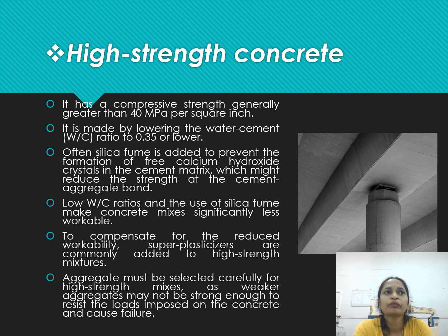So basically, when you reduce the water, look, water is added first of all for bonding. The next reason for adding water is to ease the process of mixing. This water, which is required to ease the process of mixing, is called convenience water. And the water which we add for actually bond formation, the gel formation, is the bonding water. This bonding water is very little actually, nearly 18 to 20%, but the other part is more.